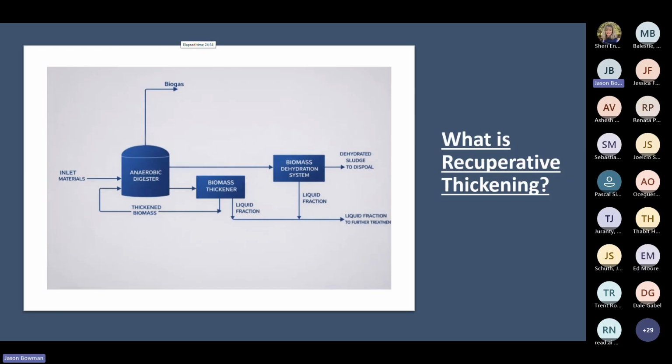operations. So what this means at the end of the day is what goes out of the DAF, the clarified DAF effluent, has much less loading and much less solids that are going to, typically, a downstream wastewater process. So we can actually reduce the loading and the burden to downstream processes with this type of process.